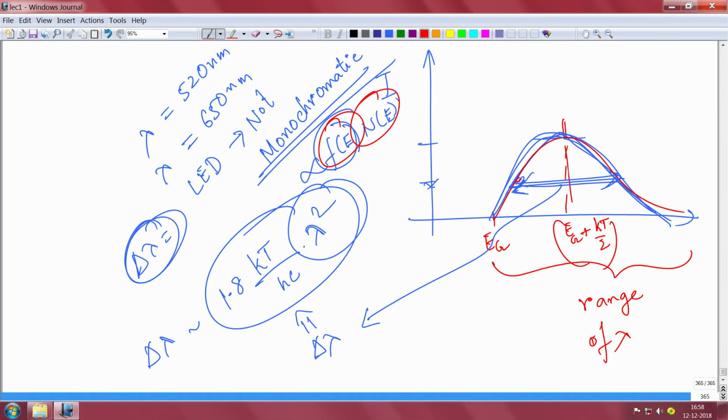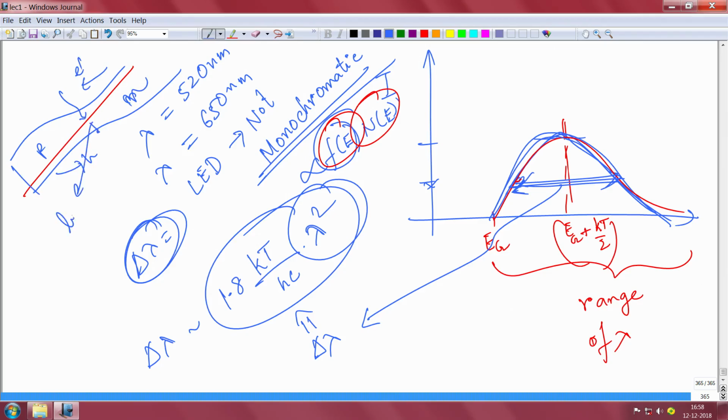And this emission that happens in a PN junction I keep talking about, right. If I talk about this PN junction, this is P, suppose this is N, on the P side you will inject holes, from the N side you will inject electrons, and they will recombine in here and emit light. That process of injecting carriers and emitting light is called EL, which is also called electroluminescence.